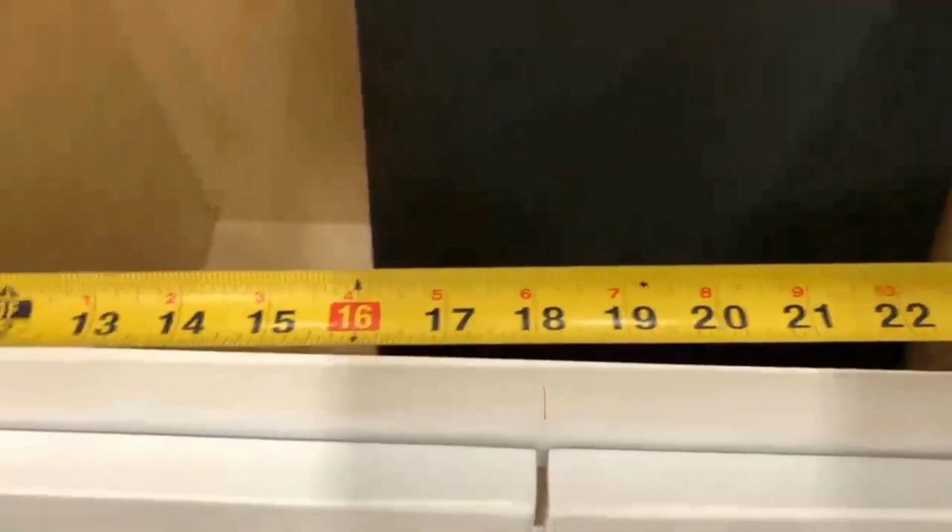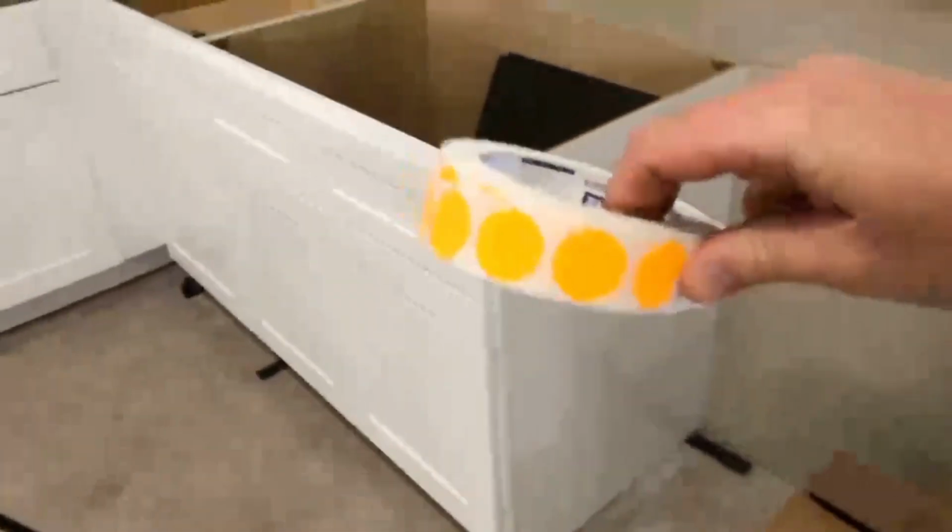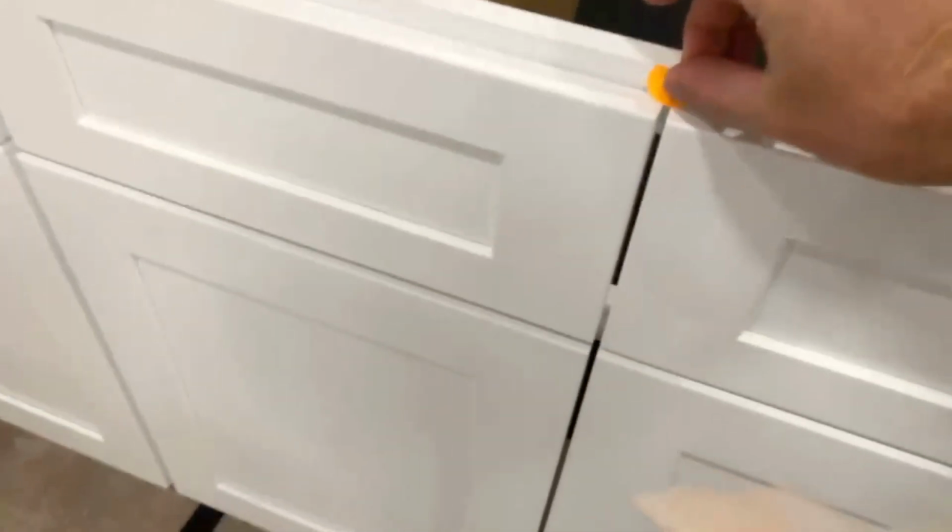Also, I like to make sure that I have, if they're fresh cabinets, new cabinets, I just mark the center of the cabinet, right? It's a good idea to always flip your tape. Make sure you don't do a mismark. I want to check my work along the way. If I had cabinets installed here, often I'm using the orange little stickies. I'll put a line on it and I'll do something like this instead.